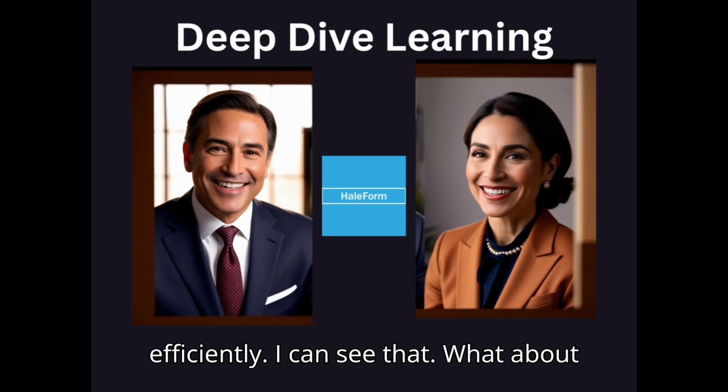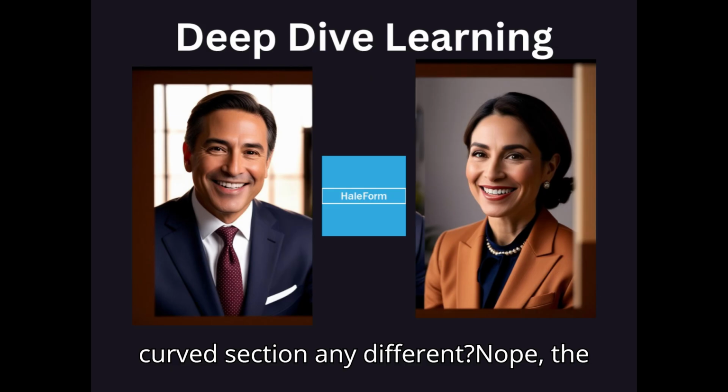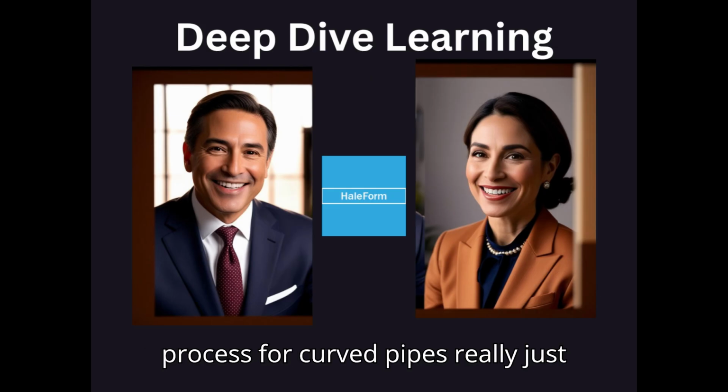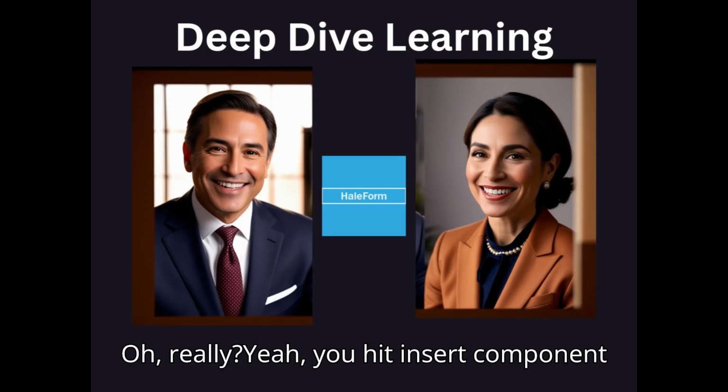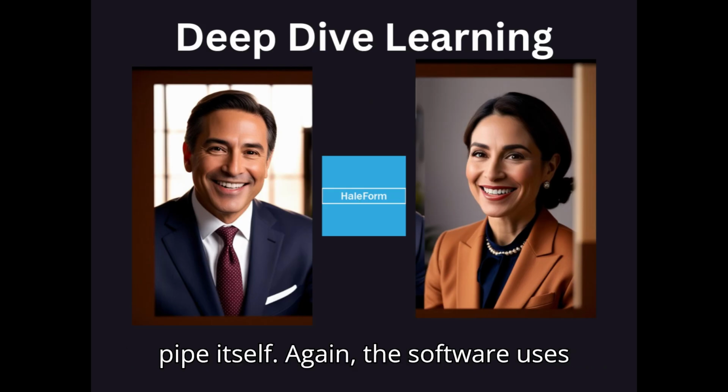I can see that. What about curved pipes? Is putting a component on a curved section any different? Nope, the process for curved pipes really just mirrors what you do for straight ones. Oh, really? Yeah, you hit Insert Component command, then you just select the curved pipe itself.